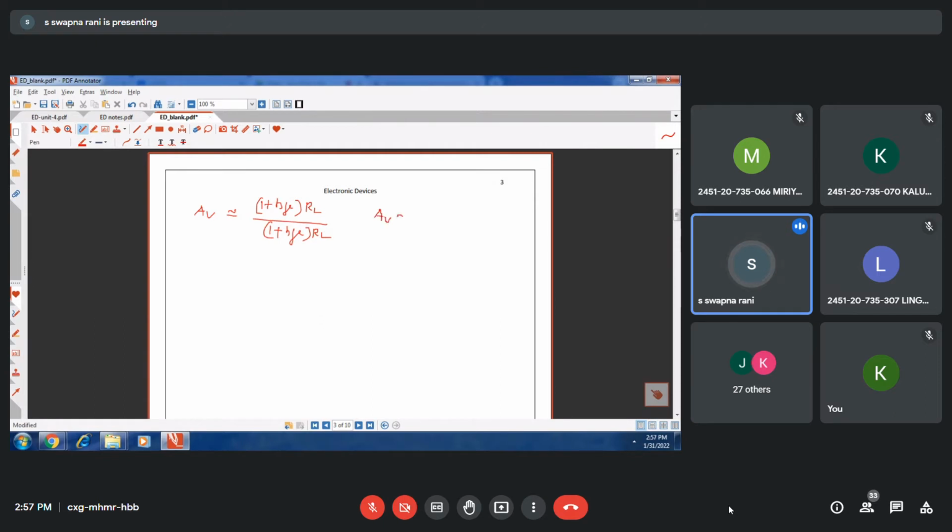If you remember, the voltage gain of common collector is unity, with high input impedance and low output impedance. Because of the unity voltage gain, common collector is called a buffer amplifier. Not amplifier, buffer. Voltage gain is unity, right? So no amplification, therefore it is called a buffer. In the comparison table we directly wrote AV equal to 1. Whether you use exact or approximate analysis, the voltage gain is approximately 1 for common collector.